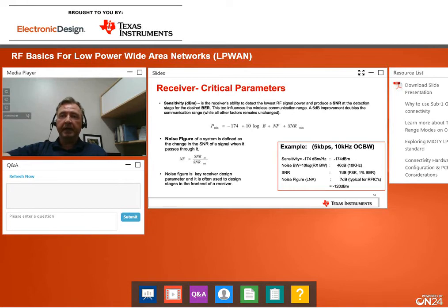The reason that a typical SoC is relatively high is that it is a compromise between power consumption, noise figure, and also that we typically have the ports merged between the power amplifier and the LNA, effectively hurting the LNA's performance because it is hooked up to the PA pins also. So this really comes down to a cost of the end equipment of the gadget that is being built.